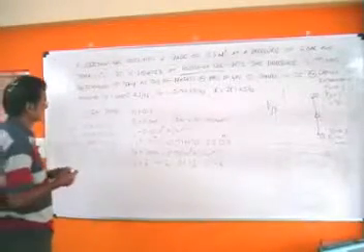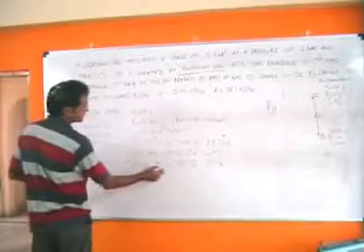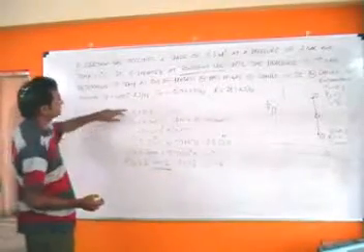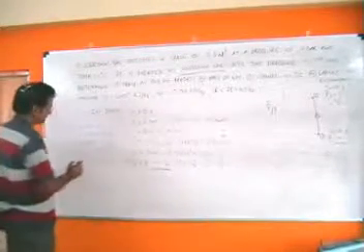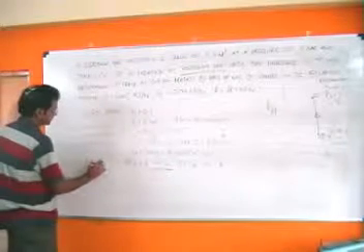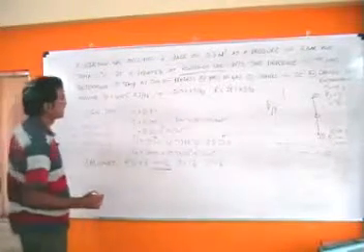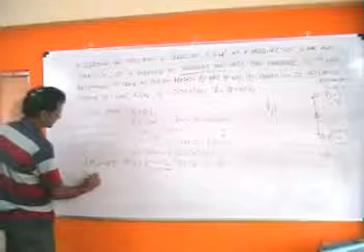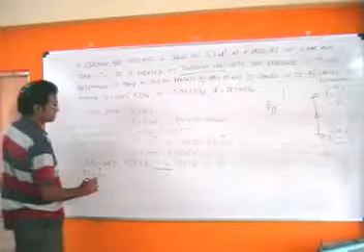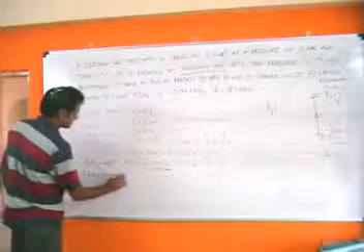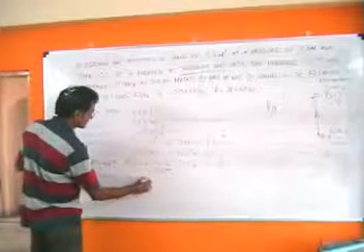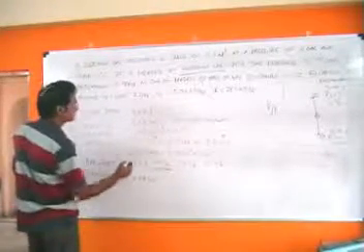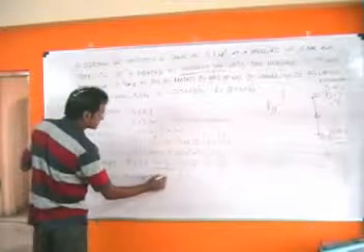Now this is calculated, now again to calculate the mass of the gas. Since we know the values of V1, P1, T1 and also the standard value of R, we can use the standard gas equation P1 V1 equals m R T1. Mind you, you need to take care of the units, which means in case of P1 we put 0.2 into 10 to the power of 6 in Newtons per meter square, the volume should be in meter cube, 0.3 equals m, which is what we have to find out, and the value of R again should be in SI units, which means 287 into T1, which should be in Kelvin, 350 degree Kelvin.